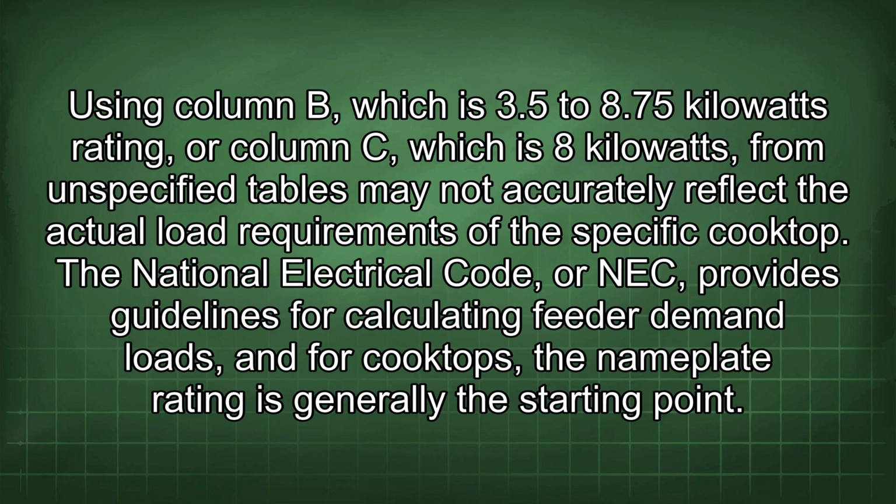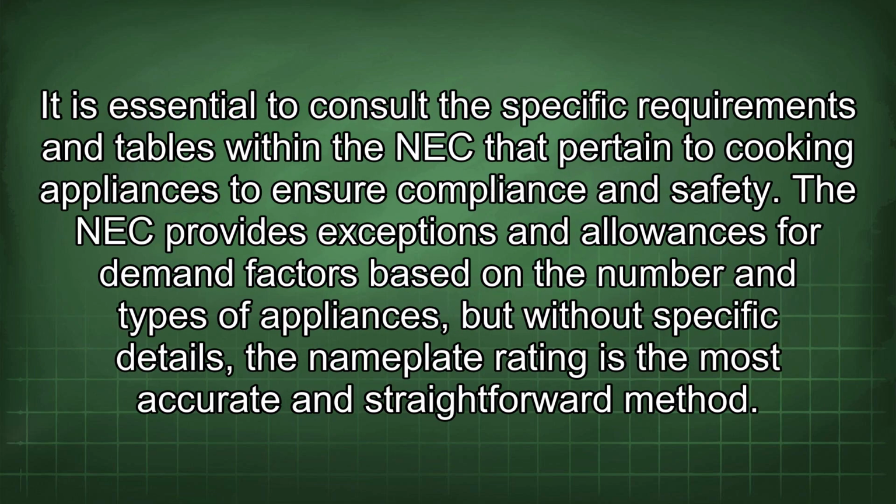The National Electrical Code, or NEC, provides guidelines for calculating feeder demand loads, and for cooktops, the nameplate rating is generally the starting point. It is essential to consult the specific requirements and tables within the NEC that pertain to cooking appliances to ensure compliance and safety. The NEC provides exceptions and allowances for demand factors based on the number and types of appliances, but without specific details, the nameplate rating is the most accurate and straightforward method.